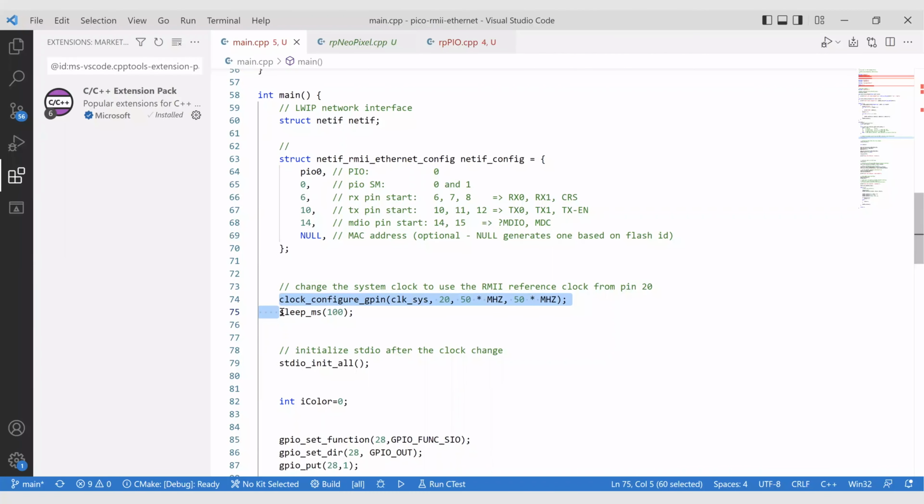What's really interesting, and could be a potential gotcha, is that the Pico will accept an external clock, but only from 2 different pins on the part. So if you're designing a part where you want to do that, you have to be careful about what pins you pick. I was working on that, and I discovered that. But you can see he picks pin 20.